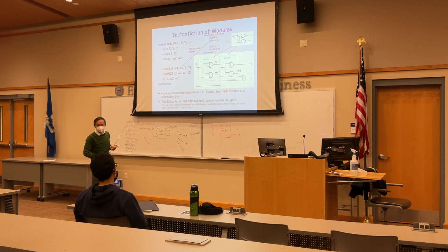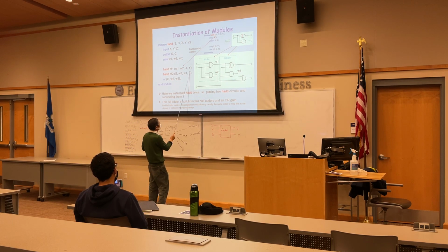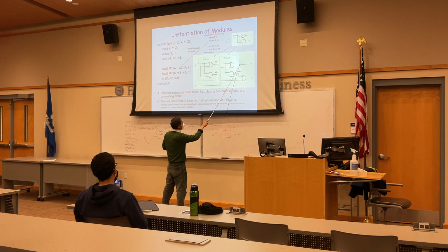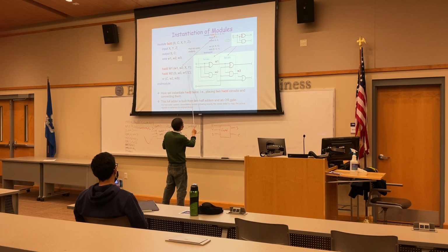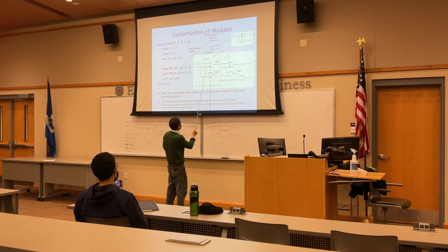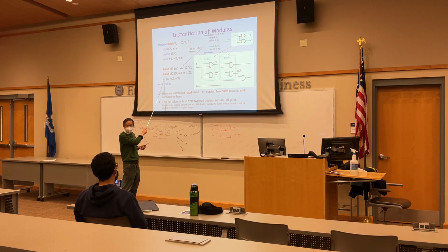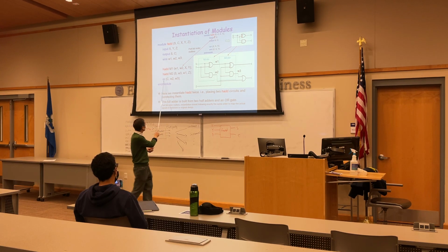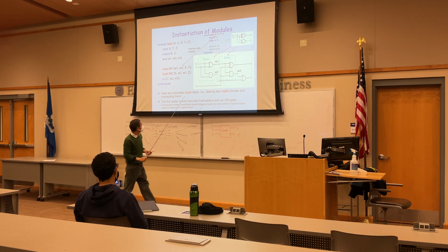The order matters. Another instance here, M2. Again, follow this same order: S, sum, WC, W1, W2 for the inputs, or W1 and Z, right? Z for this second half adder. Plus another instance of your primitive. That's easy, you got it just now. Okay, C, and the WC and W2. Done, right? End the module. Any question?